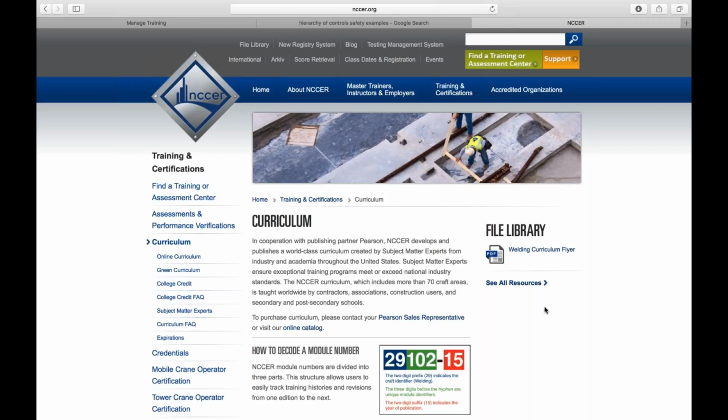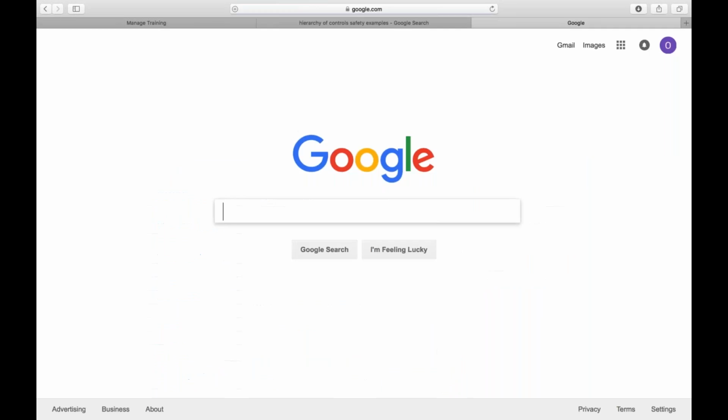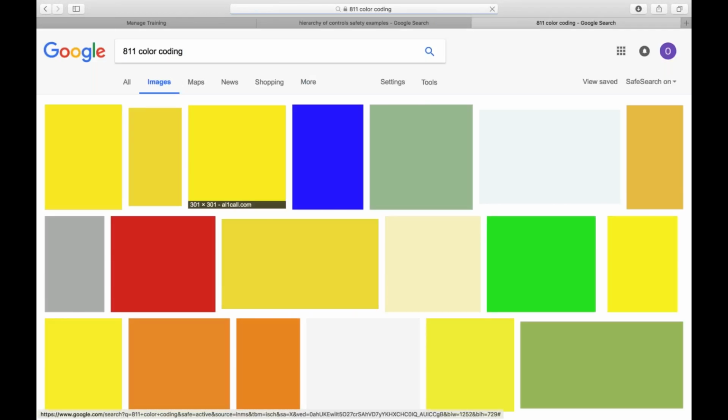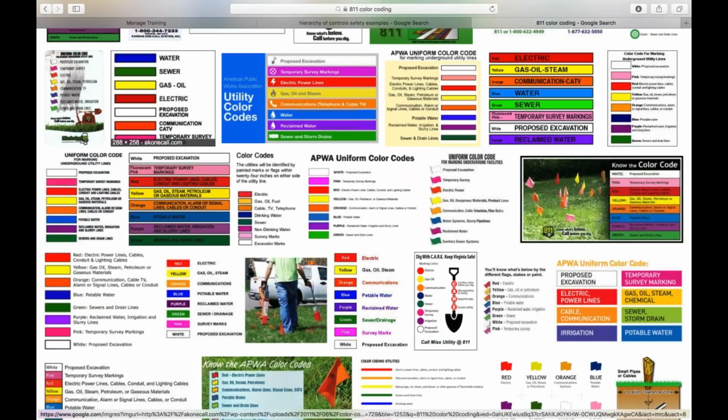And then, of course, utilities, right? Water, electricity, gas, sewer, any other. It could be radiological, okay, infrared. So just depending, right? And then have all existing utilities been located and properly marked, like we said, 811, and then following that color chart that we said, right? The 811, let me go back to it, the 811 color chart. There you go. Going back to what I was talking about, depending on what utility it is, what color they will paint it. Okay, good.